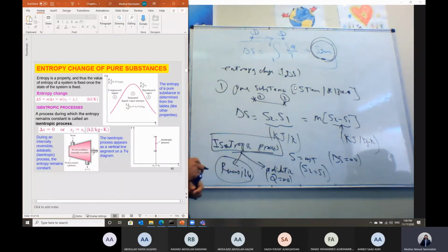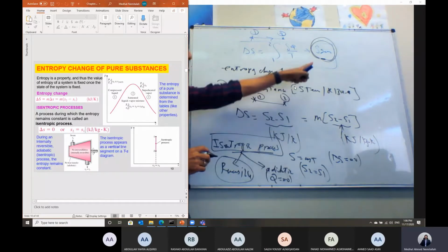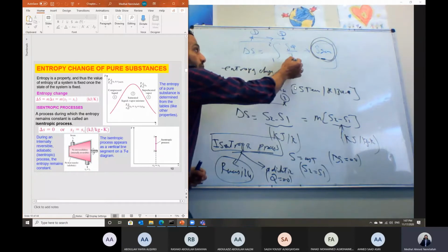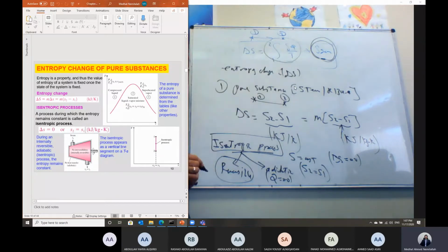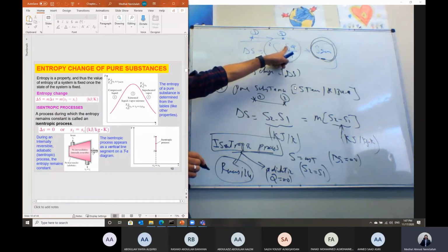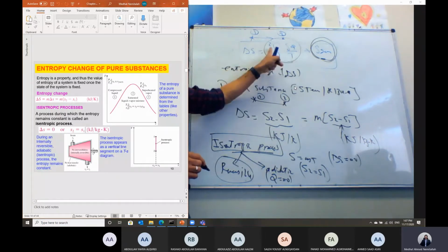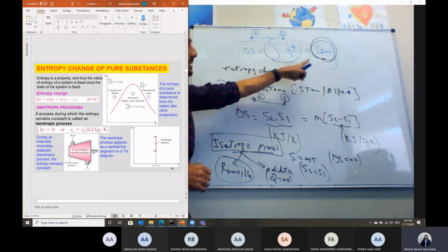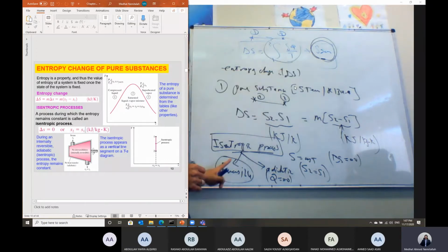We don't have any kind of losses, so entropy cannot be generated, and the entropy can remain the same. But if I want to keep this entropy the same, that means you should not have what? Heat transfer. Because if we have heat transfer to the system, in this case this term will represent a kind of entropy change. So to have delta S equal to 0, entropy generation due to the losses should be 0. That means the system is reversible.